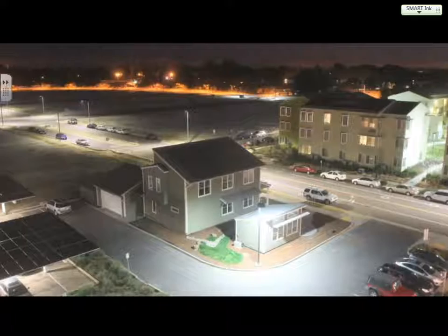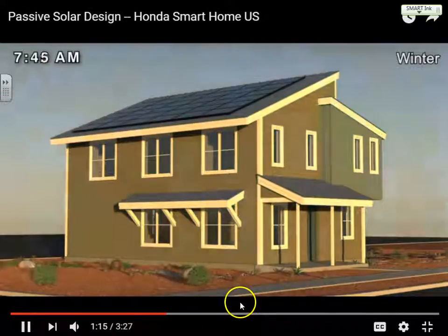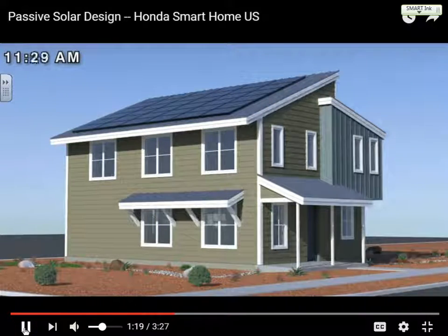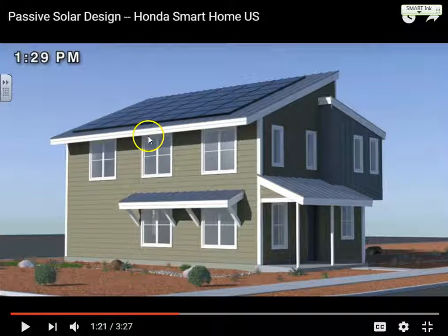Avoid the use of air conditioning. This is the south side of the building here. And as you can see, Davis happens to be a really great place to apply these passive design techniques. We are in the Central Valley. So you see these overhangs, and if you notice the time moving forward, this overhang is creating shade for those south-facing windows in the summer.